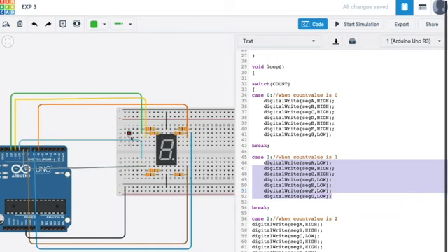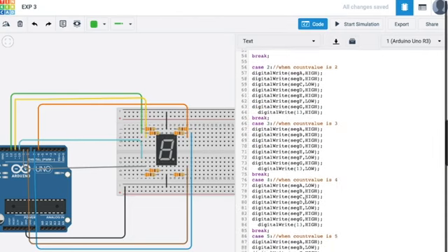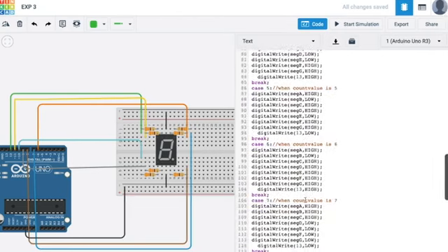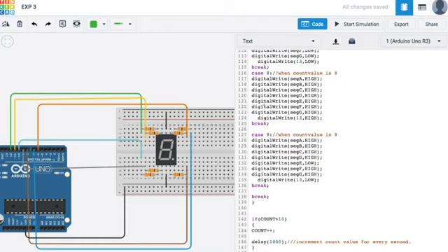That high or low value is applied to this 7 segment display through the resistor, so that these LEDs will turn on and off correspondingly. And next, we want to make a count operation. So the switch case part is okay, done. Here we have made the displaying part.